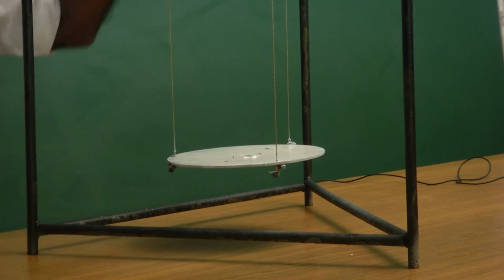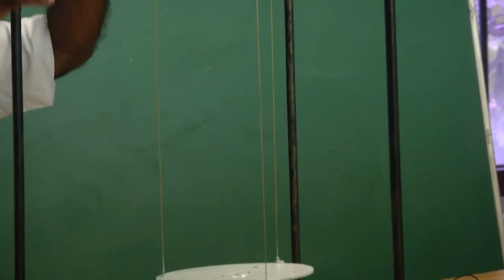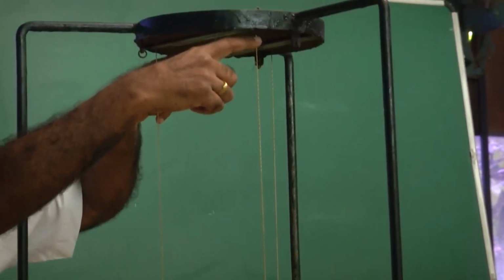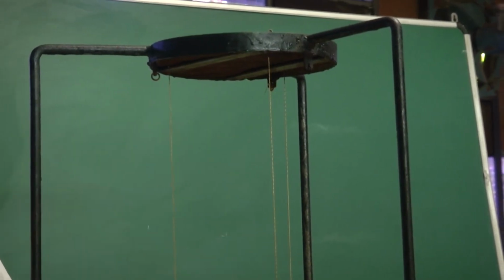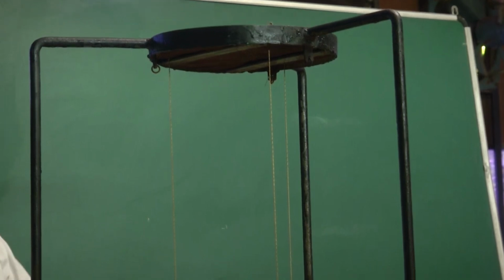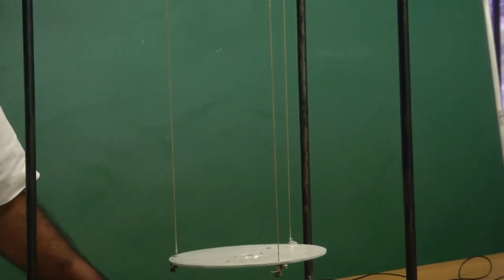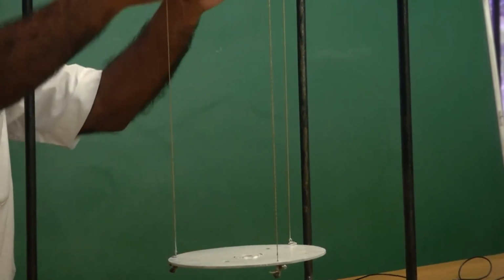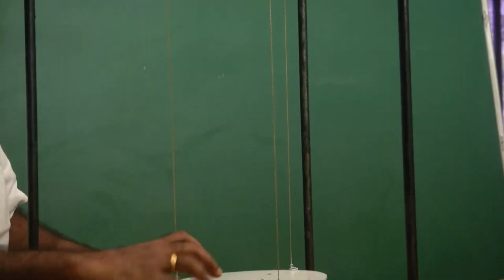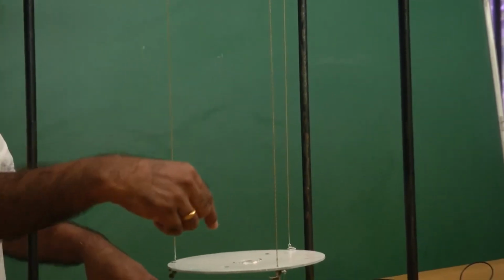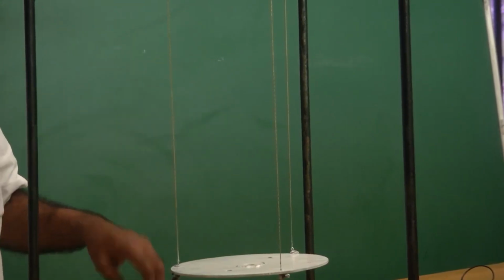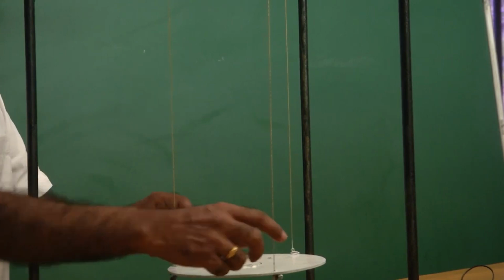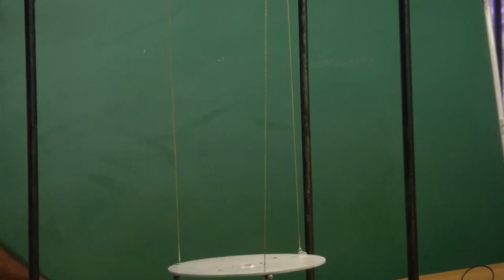Okay. So, let me again give you a glimpse of the whole setup. You basically have these three strings which are vertically aligned and connecting to the plate at the three extreme ends here. So, their radial positions are something that you can measure easily, and the strings are inextensible, so that when the plate swings, the point of connection is not lifted up as the plate swings, and this is how the swinging motion happens, and that is our typical vibratory motion.